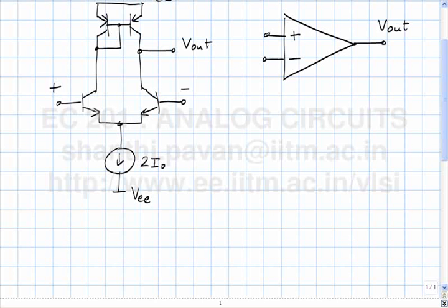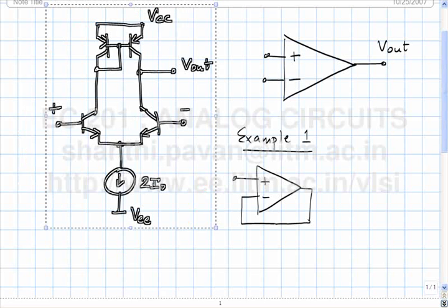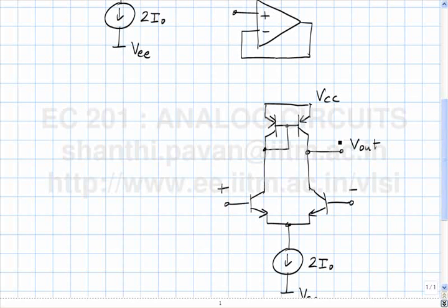circuits that we can build with an op-amp, one that doesn't require any external components at all, and that is the unity gain follower. Plot this as the op-amp and see what happens inside. So please notice that Vout is connected back to the negative input terminal, and if you did that with the real circuit, what you will have is a connection of this form.